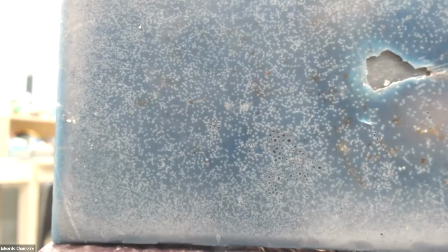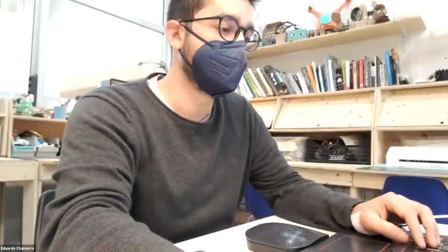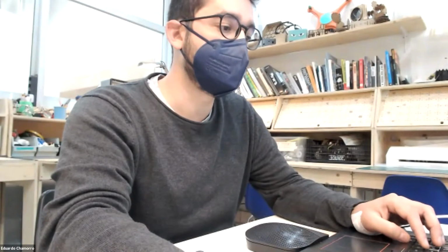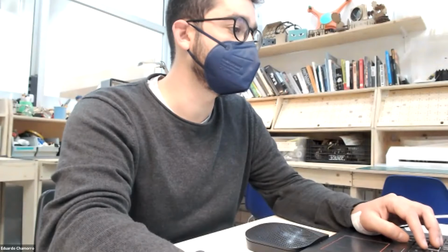So it's a little knowledge. Then we have the step over. That is a value that you will not use a lot now. You will use it in 3D milling. But let's see, this is the end mill, and you want to cut all this material. It means raster all the material, destroy it. This is about how much we move on the side. I will change the color of this end mill.